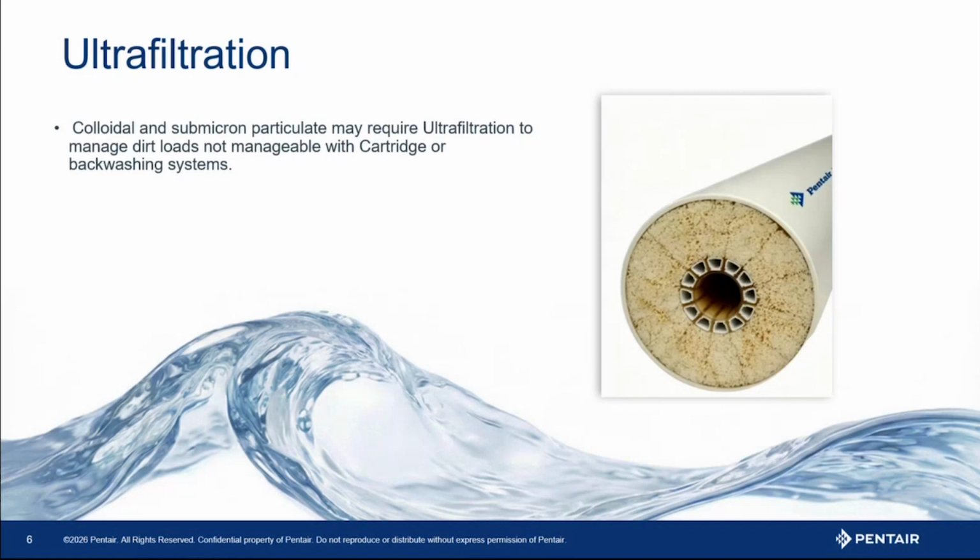And many of these products will have a biological application to them as well, where they're reducing bacteria as well as potentially virus, followed up with a UV, and you've got a pretty complete dirt load and protective system there. Just be aware that this may be the solution to your problem if you're dealing with submicron stuff.